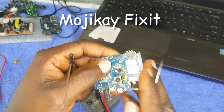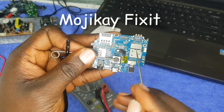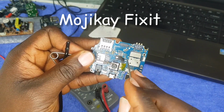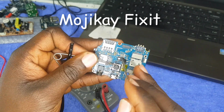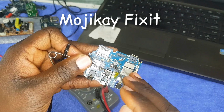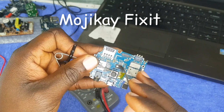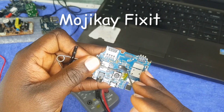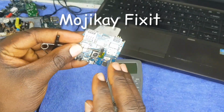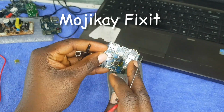And how do you identify a resistor that is bad? One, it's burnt, you see the physical burn, or number two, it can short. Resistors can also short. And number three, it will not give the actual reading. For example, if the resistance of the resistor is 1K, it will give you 200 ohms. If it gives you 200 ohms, that means the resistor is bad. If you take your reading with the multimeter and instead of giving you 1K it's giving you 200 ohms, that means that resistor is bad. I hope you guys understand what I'm saying.